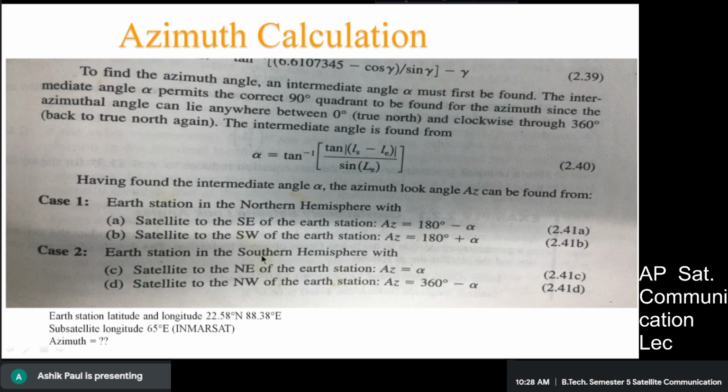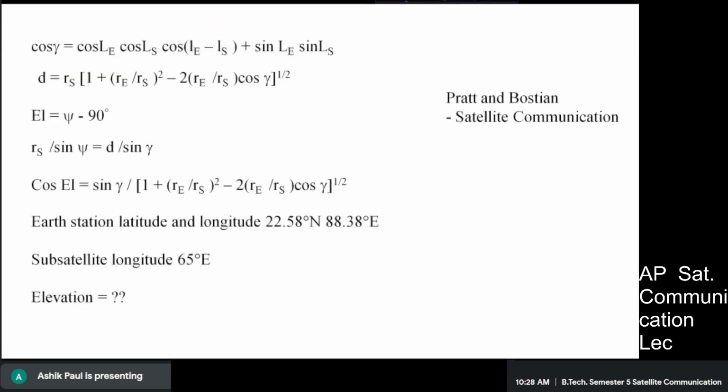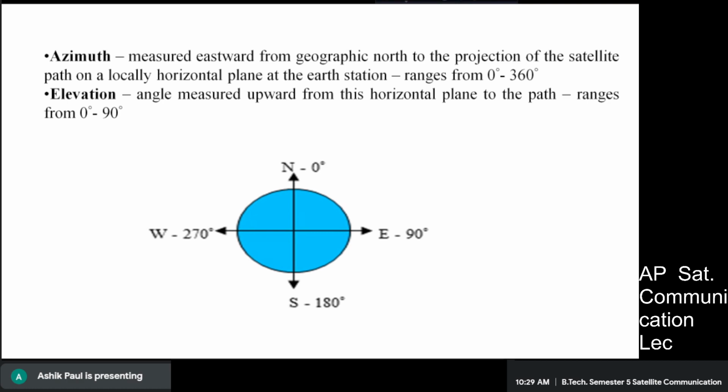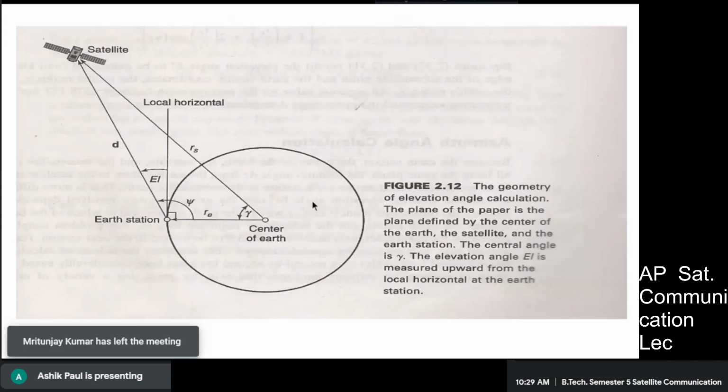And if your Earth station is in the southern hemisphere, then of course all these things that we had talked about, locating a satellite with respect to India, will reverse. Suppose a geostationary satellite is being tracked from, say, Australia or South Africa in the southern hemisphere, then the satellite, being located above the equatorial plane, will be in either of these two quadrants.